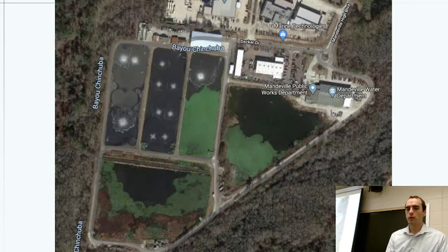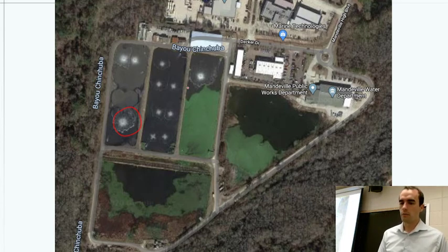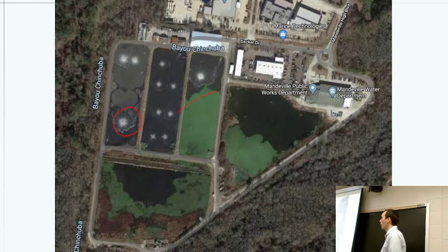is in these three here we've got aeration. So these are fountains or something that's spraying water up and around. It's wastewater, by the way. So I believe all three of these are getting aerated and mixed to an extent. You can also see a lot of algae, cyanobacteria growing, kind of visible from here. And then essentially these will be collected and then be treated with ultraviolet light and then discharged into the surrounding